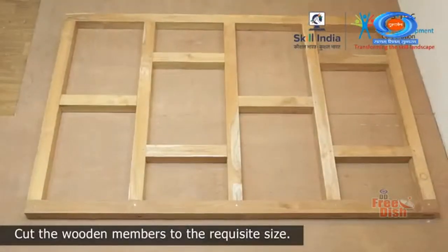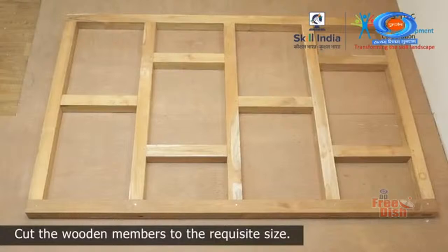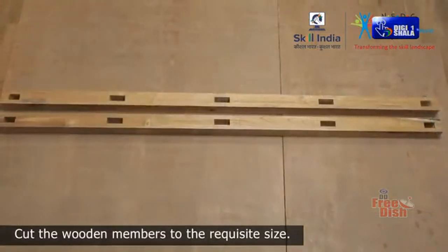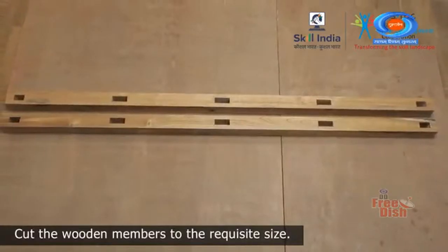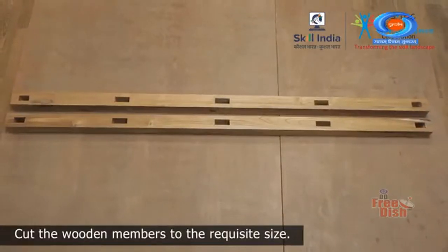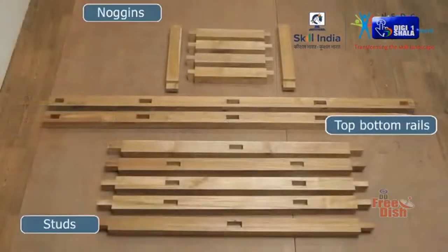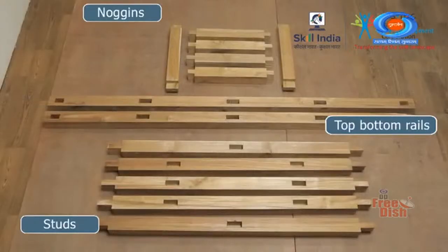Build the partition skeleton on the floor and raise it afterwards. To build the partition, you must place the studs between the top and bottom members as shown in the work drawing. Here we will use a combination of common mortise and tenon joints and stub mortise and tenon joints to assemble the partition.